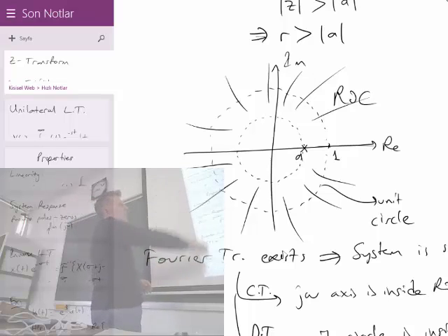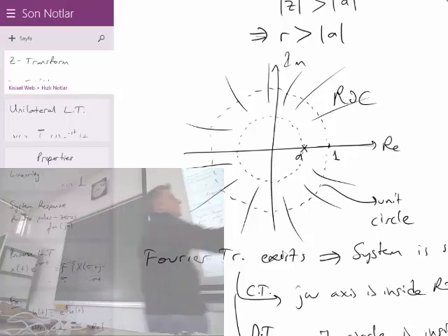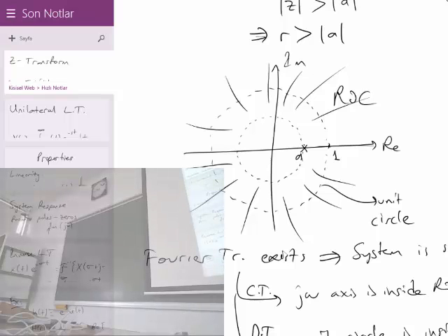You have stripes on the Laplace plane, remember that? And those lines or stripes, vertical things, are rotated into the z plane. This is the j omega axis rotated and bent to form a unit circle, for example. It's a mapping like that from s to z.